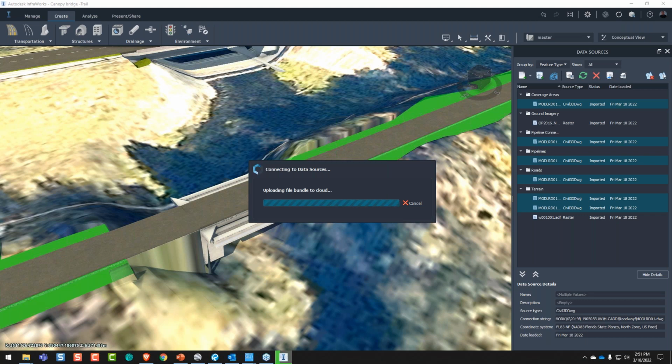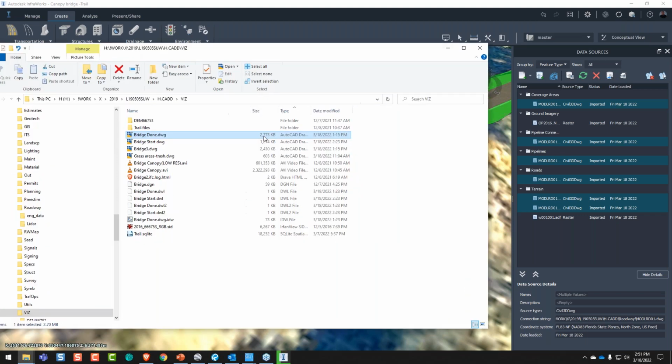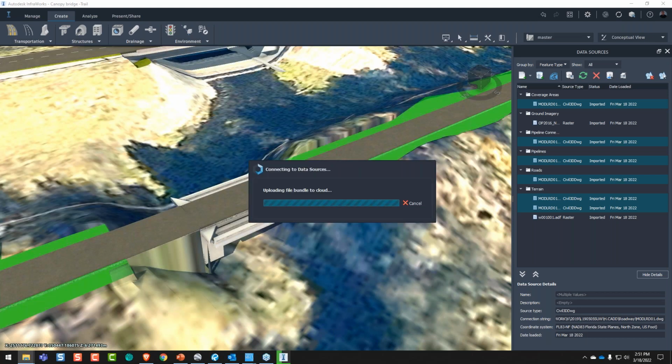If you'll notice here, what I like to do, by the way, is this is pretty small. My bridge file was pretty small. I'm not done, but compared to, let's say, the model file, I always do a WBlock usually. I'll WBlock out the file to a totally clean DWG file, because you want as small a file as possible for uploading and for downloading and all that good stuff. You don't need to have all the extra crappy, quote unquote, data in there. Okay, so just minimize the data, because that's all you need.